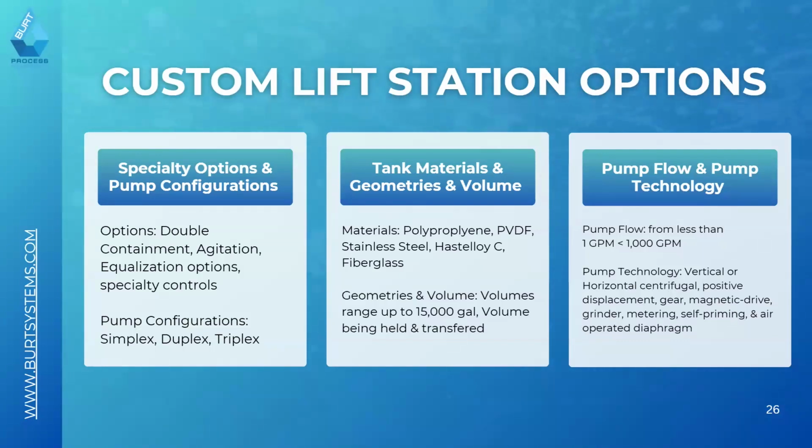For example, with a thermal waste, you can have a sanitary stainless steel design for a lift station. For different carcinogenic waste, you may have sealed fiberglass with buried tanks. PVDF for high temperature waste streams, and polypropylene is fairly common.